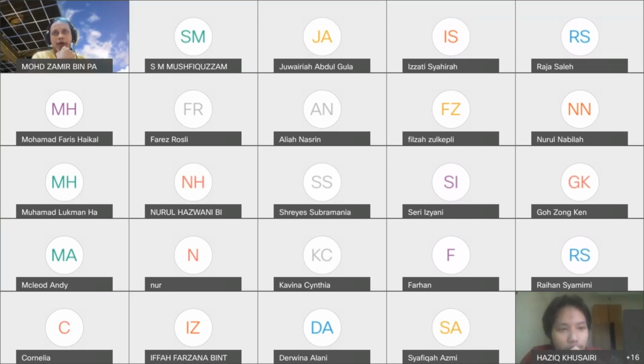Okay, so when we want to do the calculation of density of free holes, we'll come to the next topic anyway. When you want to calculate the density of free holes, you need to do it in the valence band, because you need to relate to NV. When you want to calculate the density of electrons, you are actually referring to the electrons being excited. Therefore, you need to relate your n equals NC times the Fermi-Dirac distribution function f(E), but for holes, NV times 1 minus f(E), right?